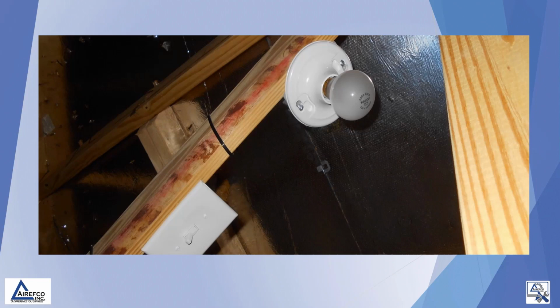To make a long story short, what they finally found out was that the installers had wired the condensate pump into the light switch for the attic. So every time that the technician went up to check on the furnace, he turned on the light and the condensate pump worked fine. When he left the attic, he turned the power switch for the light off, thus turning the condensate pump off too. And then after a couple of hours, the furnace would fault out on failure. So make sure you don't wire your condensate pumps into a light that you turn on and off when you go up to the attic.